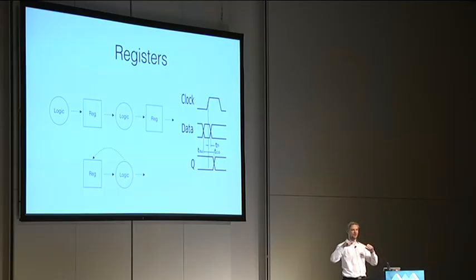And the reason this works is because the time it takes for the combinatorial logic is not small, not infinitesimally small, but has a certain delay. And so it will ideally arrive prior to the next rising edge, but after the rising edge actually occurred.